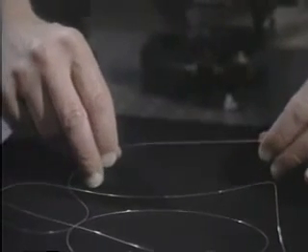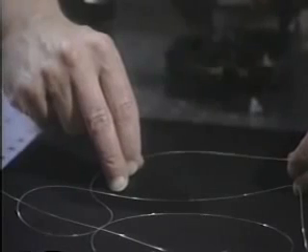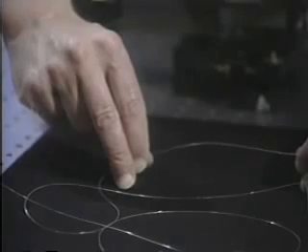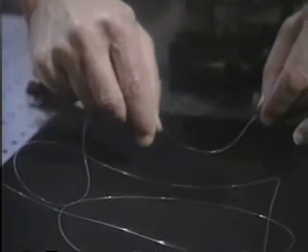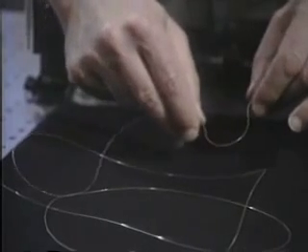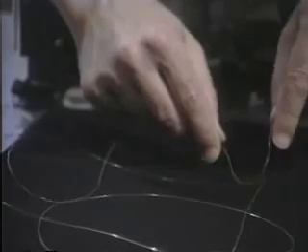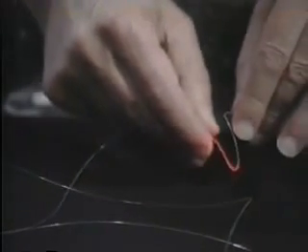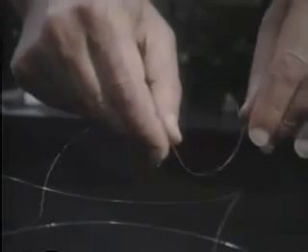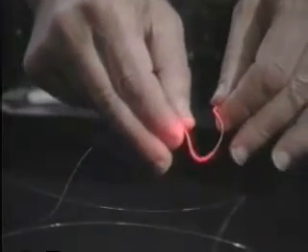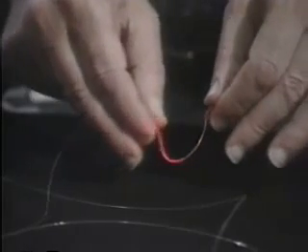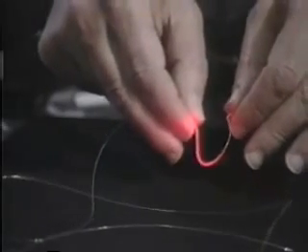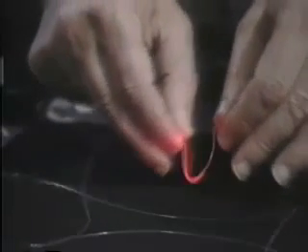Now here's a piece of fiber, and you can see that there's no light scattered from the fiber. Now all I have to do is bend the fiber, and you're beginning to see light that gets transmitted out of the fiber, gets essentially kicked out of the fiber because of the bend. The reason for that is you start going against the rules of propagation of light in a fiber.